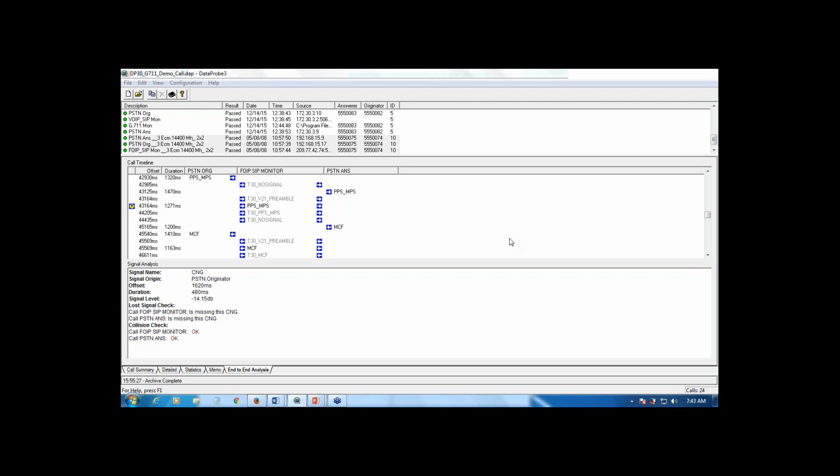That requires a buffer at the far end that is assembling these packets and presenting them continuously to the gateway to be integrated back into an analog signal that the other fax terminal can understand. This ability to buffer up these packets and present them continuously is called a jitter buffer.